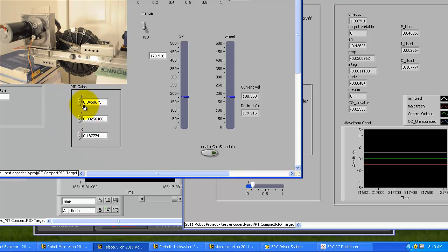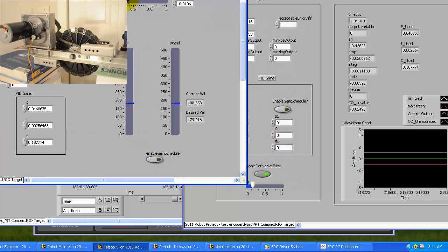up, I would use one set of gains that had a higher aggressiveness. And then for the reverse case, going with gravity, I would have another set of gains that was less aggressive. Now, you need to take gravity into account when you calculate your load on the motor for each case. And when you have an unbalanced load, you've got to split it up into two. Calculate the gains for the forward and then calculate the gains for the reverse in two separate scenarios.